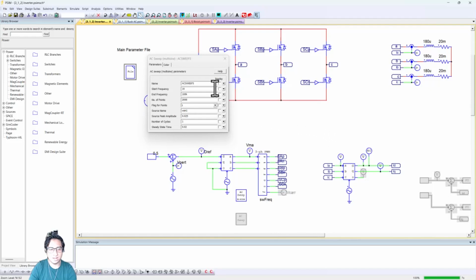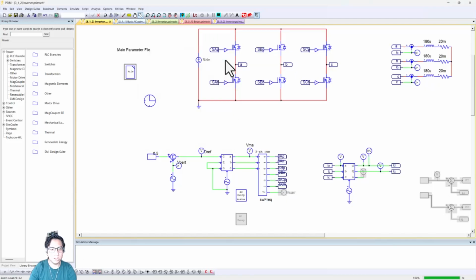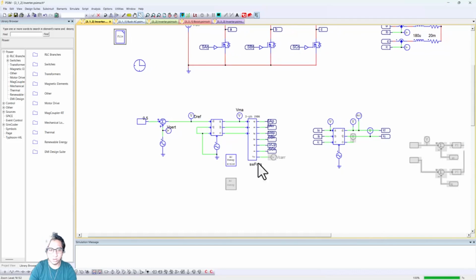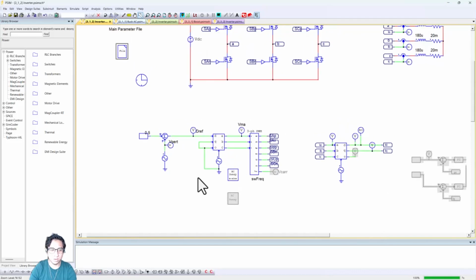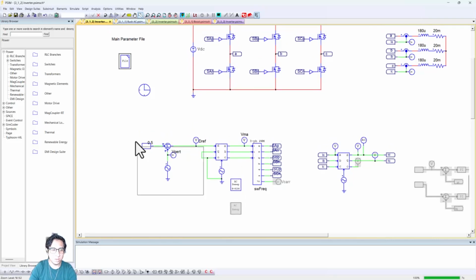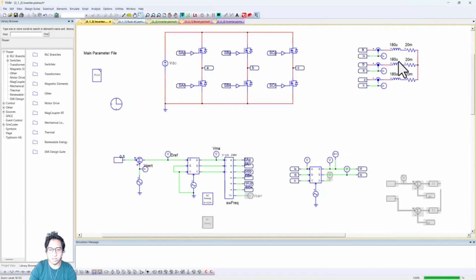And yeah, this is not going to be helpful. So let's start with something that's half the switching frequency, right? So 10K. And this actually is more representative of what we want. Just maybe a bit more detail, which I overlooked on this. We are doing DQ control, or we are expecting to do DQ control. So we are doing a sweep on the D axis and looking at the D current at the output here, right? So that's our input and the output for the AC sweep.